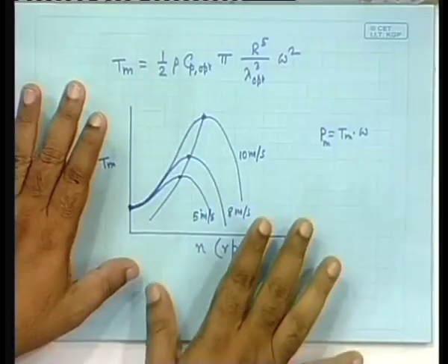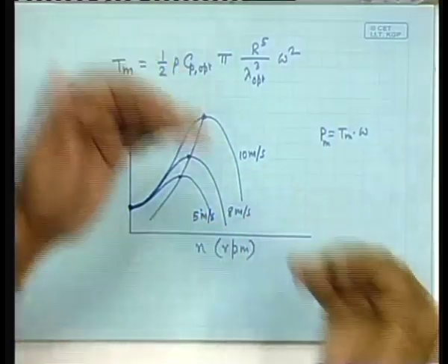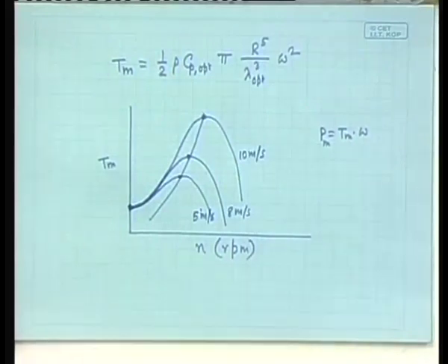So, at different speeds you will have a particular torque, this is the generated torque, and there will be a load torque. In this case the load torque is the torque given by the electrical generator. I do not know if you have this concept clear. Supposing you are supplying an electrical generator with some kind of power, that means you are rotating it, you are giving a torque.